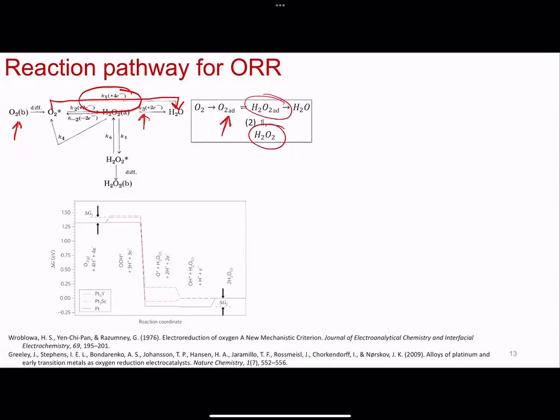And now you have peroxide in your system. And peroxide can be corrosive. So then it starts etching your platinum, and then you have loss of catalyst, and you then have decreased efficiency in your fuel cell, right? But peroxide could also eventually go to water. But the short of it is you want to prevent the 2-electron reaction from happening.